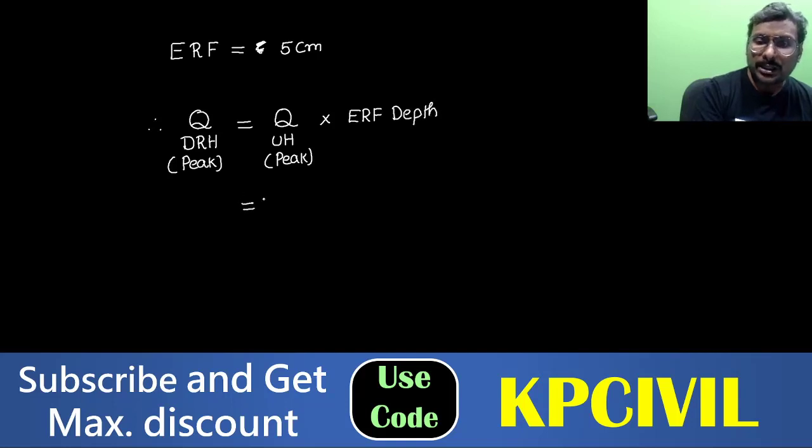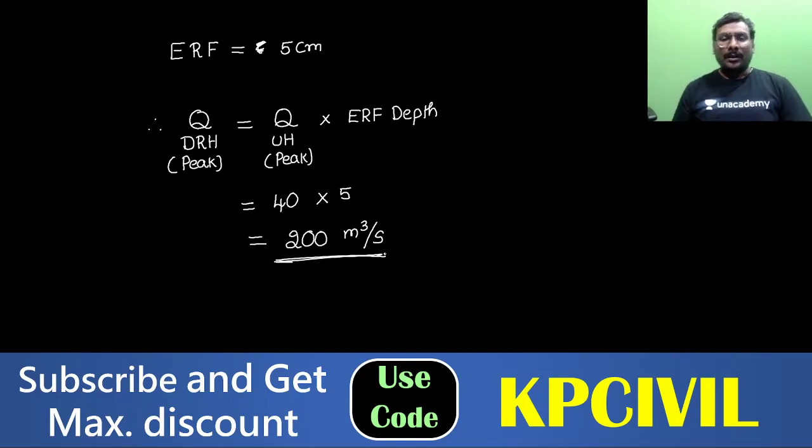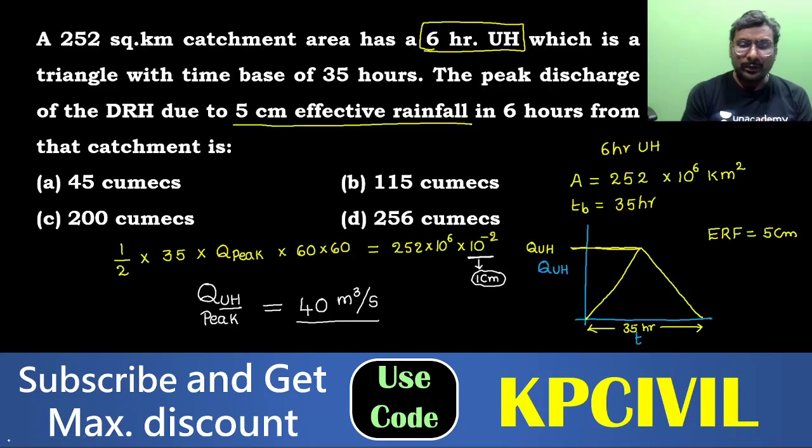Peak discharge of unit hydrograph 40, effective rainfall depth 5. So what you will get? 200 meter cube per second. This is the answer. Here, peak discharge of unit hydrograph 40 into effective rainfall depth 5, so 40 into 5, 200.